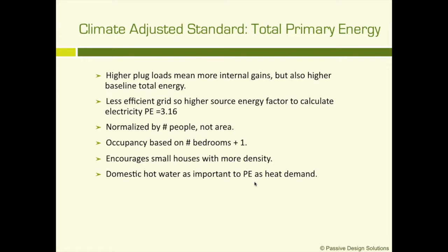And we're noticing that the domestic hot water is as important to the PE as the annual heat demand, because we're typically using a ductless mini split. That domestic hot water component of the energy budget, as I call it, is something you really have to keep a watch on.